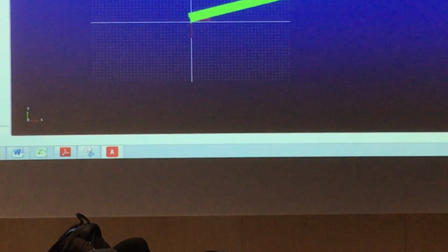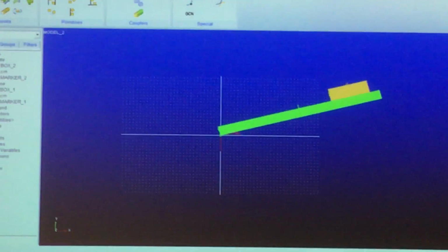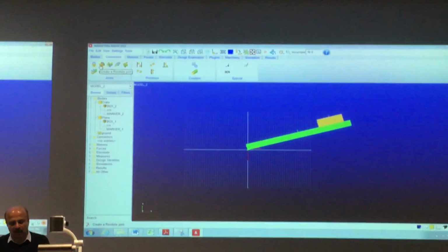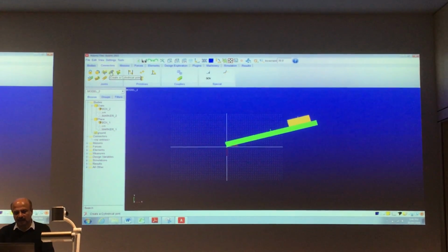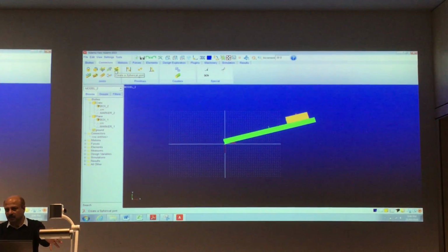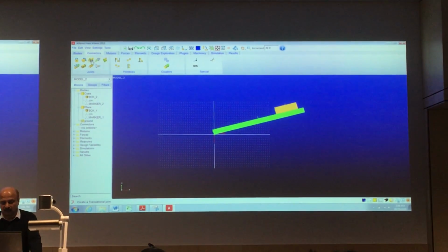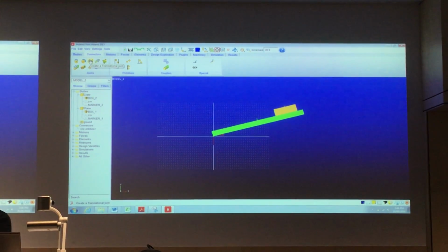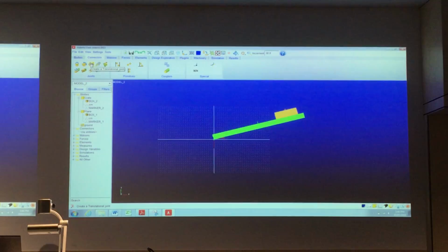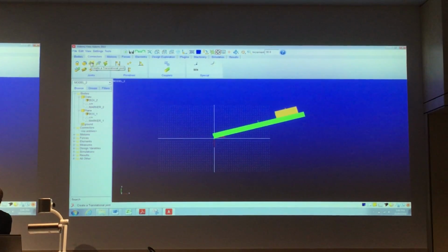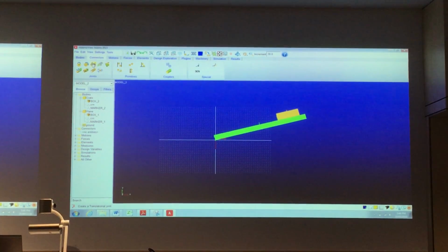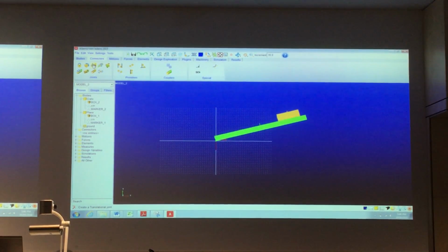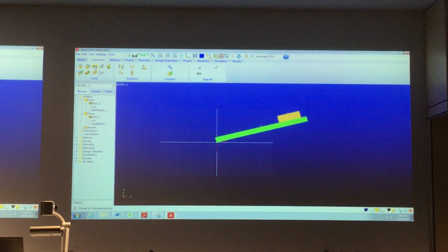This is also a bit of a tricky part, guys. Go to the connectors here, after the body. You can see the connector, and we can see a lot of connectors: rotating connectors, sliding translational connector, and this is a cylindrical joint. There are so many options, and we can create some more options here. What I am interested in is just translational, between this plane and the crate. A translational joint is just sliding. It is not rotating. It is not supposed to rotate, it is just sliding.